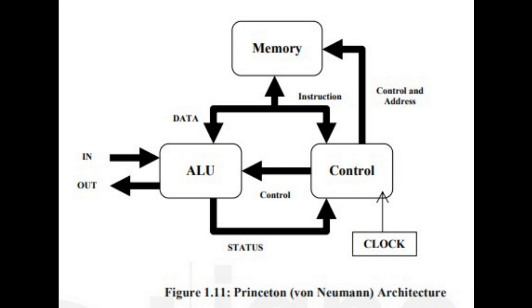The name, von Neumann architecture, has been attributed to any computer where the stored program and data are not transmitted simultaneously because they share the same medium of data transfer, called the system bus. This is called the von Neumann bottleneck, as it restricts simultaneous access of data and instructions, and thus may result in reduction in the performance of the system. However, the single path simplifies the design of the von Neumann machine. In comparison, a Harvard architecture machine uses one dedicated bus each for address memory and data memory respectively, and therefore is more complex. The basic characteristics of von Neumann architecture are summarized below.